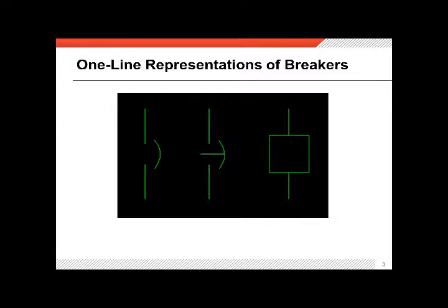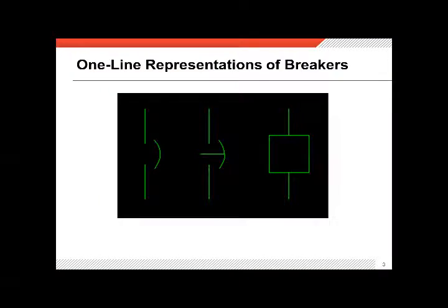In an oil breaker, you'd have the bushings up on top, then conductors would come through the bushings into a large tank of oil, and there would be a big plunger in the middle with a huge spring on it, and it looks not entirely different from that depiction, where there's actually two contacts and the thing moves up and down. Anyway, I've always assumed that is where we got that symbol from.